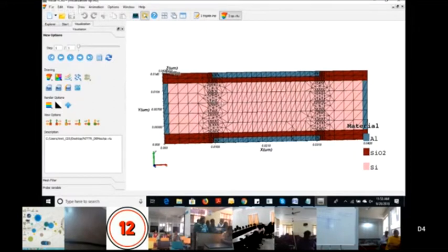So that's why this is a tight mesh. We are making a denser mesh here because we want to make a junction here. This is an NP channel and source junction, or channel and drain junction. That's the region we require. Where we find a PN junction, on those areas we require high meshing.